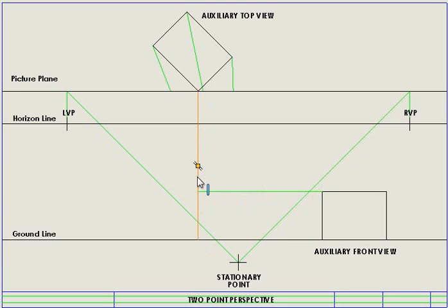It's something that helps me remember where all the information that my auxiliary front view has is going to be contained. So I've got one and a second point on my information bar. I'll also use this as my information bar because this point over here actually represents 2 points. Remember, this is my top view. So that point there has a top point and a bottom point. There they are, 1 and 2. So does this point, it has a top point and a bottom point. That one there exactly the same, and this one here exactly the same.